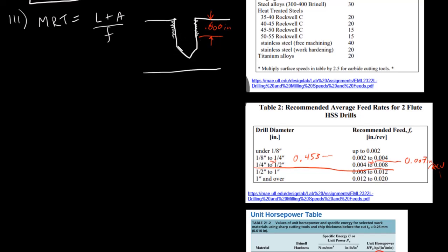But let's say we always need to leave a little bit of space here so that the tap can go into the hole and not bottom out into this chisel area. And this is A. And you could calculate the angle here and do some trigonometry to figure out, well, this isn't a very good triangle.